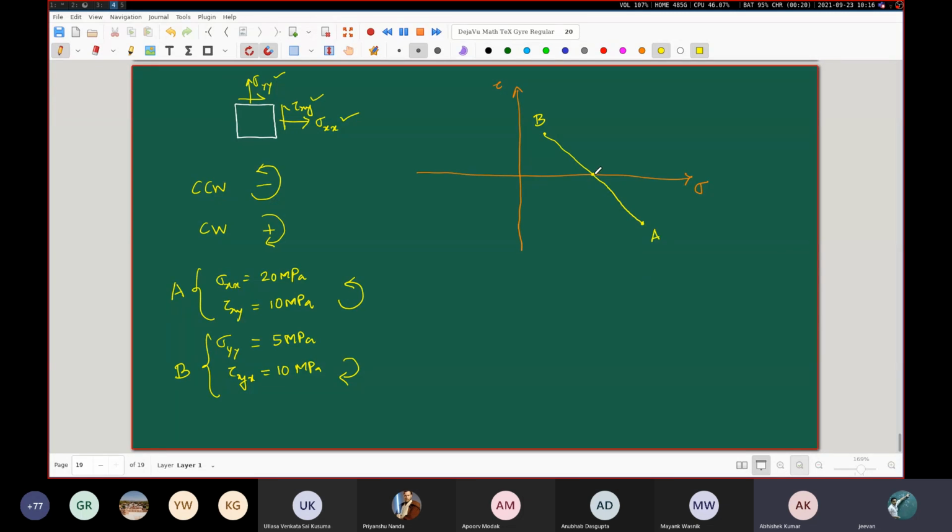So that will be the center. Now you know the center, you also have the radius. You take a compass, put the pointed end here, put your pencil here and draw the circle like this. So this is completely a graphical construction. There is no role of the calculator here, and please accept that this is a circle. Okay, so this is supposed to be the diameter of that. So this is your Mohr circle. That's it, finished.